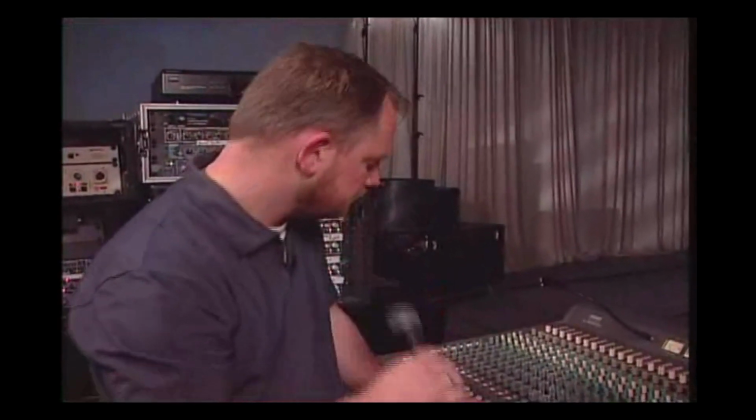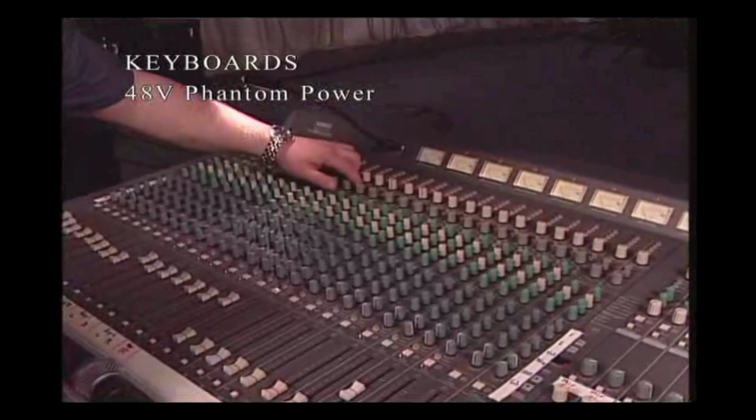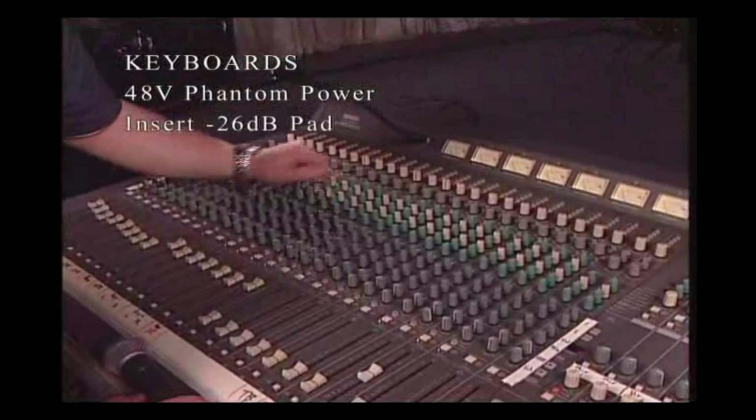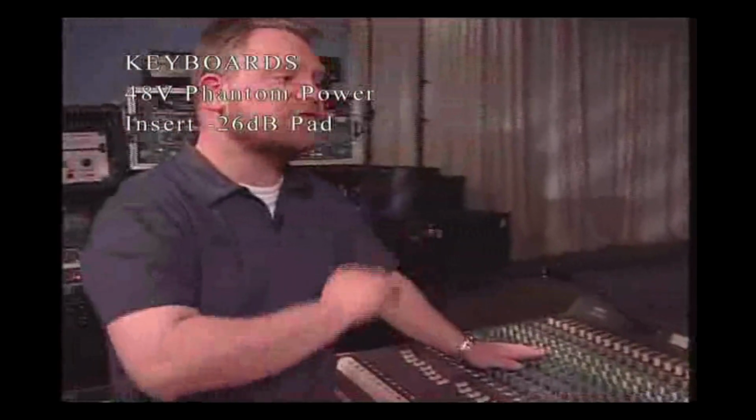All right, stand by. So explain what you did there, Dave. Well, first of all, I turned up the 48-volt phantom power because I'm running it from a DI. Then, I padded down the inputs 26 dB and adjusted the input gain. And I left the EQ flat.